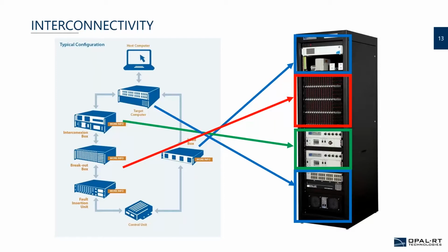So rapidly, what we will have in there, and I'll go into more detail on each of the different items: you'll have the controller, obviously, but you also have the simulator itself, conditioning units, because the IOs aren't necessarily always a direct connection, different loads, and the fault insertion unit and breakout box, which brings me to the next slide.